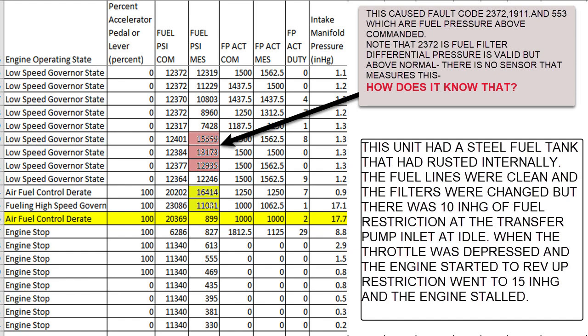It quit running. And you can see in the fuel pressure actuator commanded current column, the last thing you see is 1812, and then you see the 0. When you see the 0, the engine is stopped, it's done, and the ECM has said, the party's over, boys. And you can see the operator still had the throttle at 100%, and then he finally let go of it.